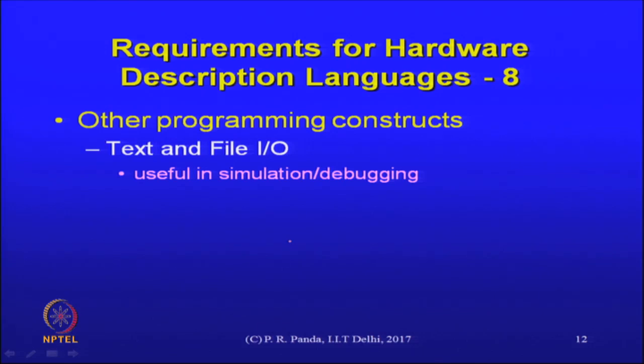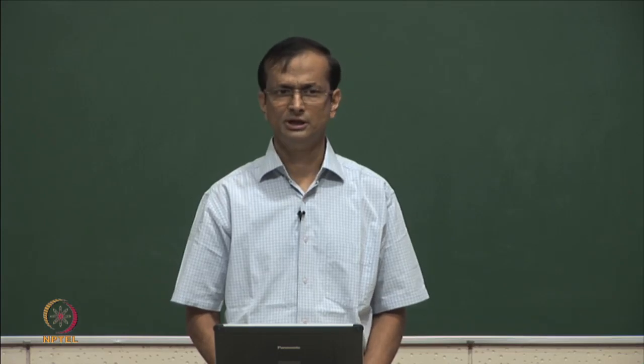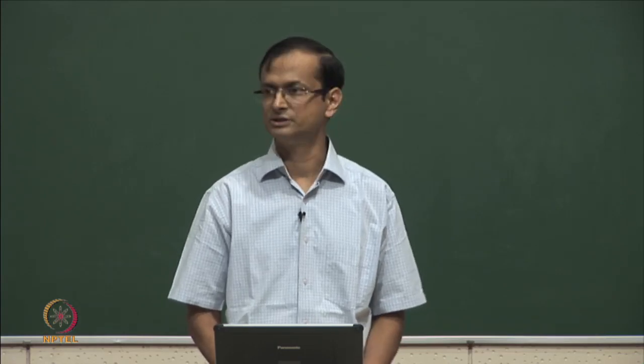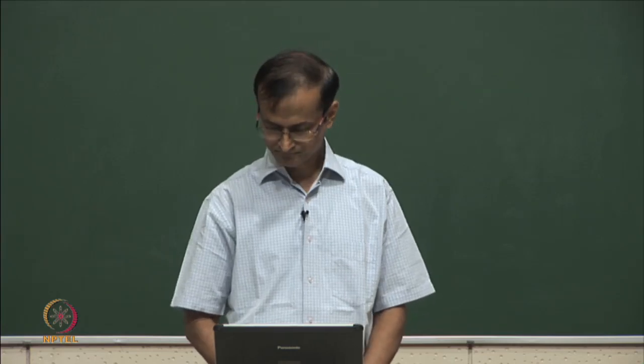Design is not the only thing that we are doing, we are also doing lots of other things. We are generating inputs for testing. That is not part of the design, but how do you generate that input? It is considered so basic that the design language itself provides some mechanism for you to specify the input itself. Or equivalently, if you just extend that, you should be able to specify your input in a file, and in your HDL you read that file and provide that as an input to the design. So, those things are part of an overall design environment, and modern HDLs do provide some mechanisms for that.